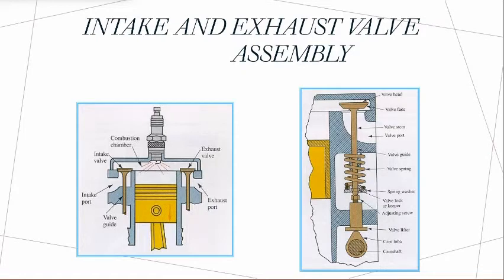The most popular shape of the poppet valve for automobile application uses a small cup at the end of the stem. The valve stem is placed in a guide hole made centrally in a circular passage in the cylinder head. The valve disc head opens and closes the ported passage leading to the cylinder during in and out movement of the stem.